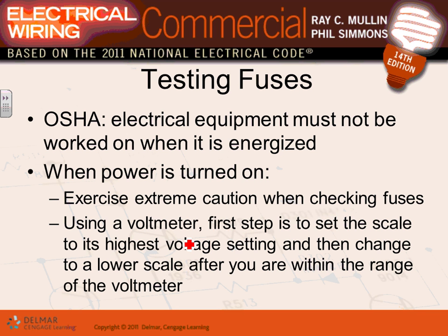But here are a few things you can do when you're checking a fuse. If you want to check whether the fuse is open, open the disconnect, remove the fuse, ring that fuse. If it rings, low impedance, it means it's okay. If it's very high impedance, this means it's burned.